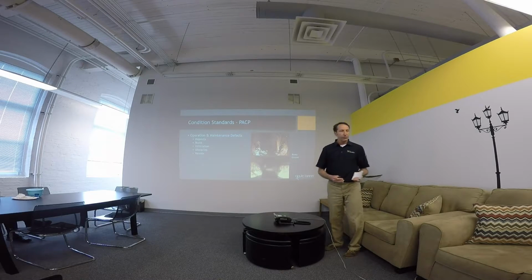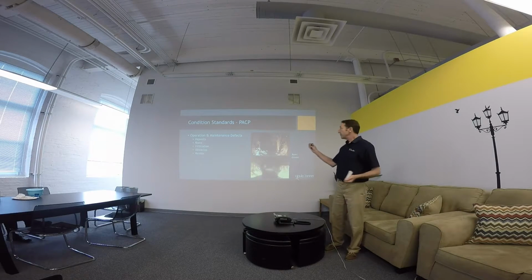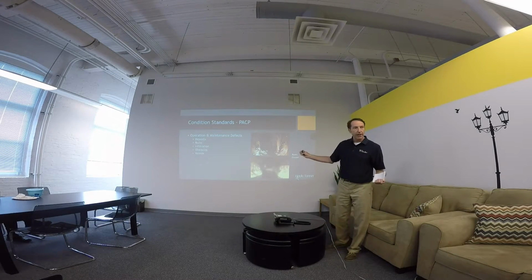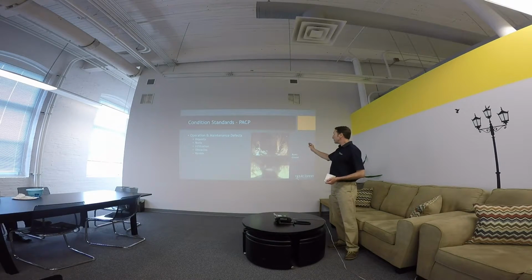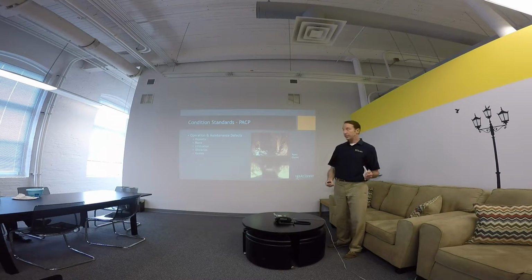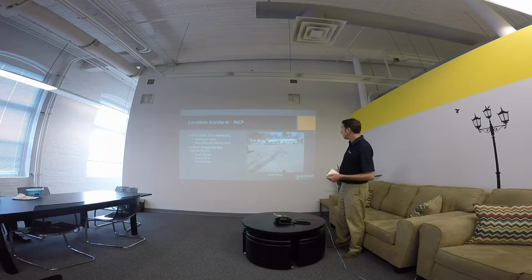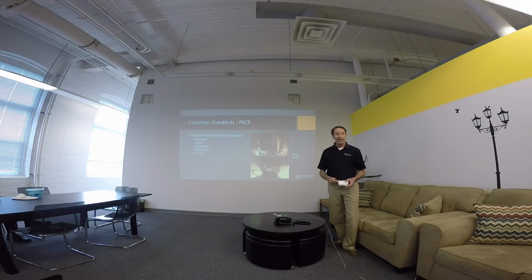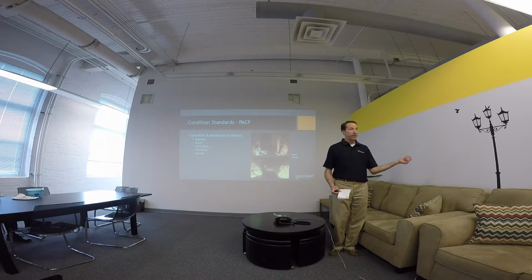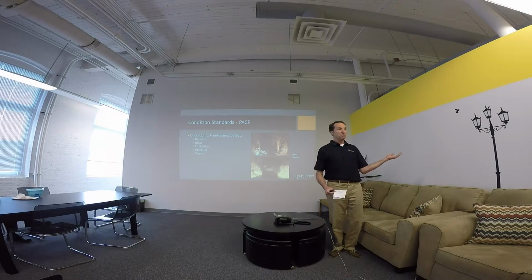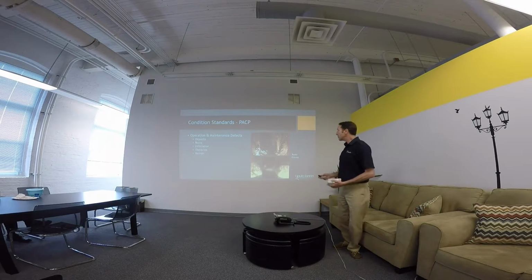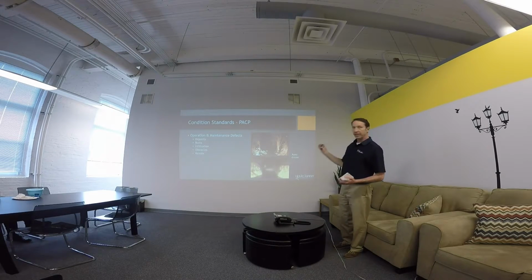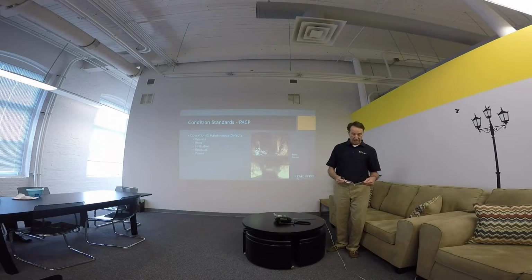I just showed you a few structural issues. I'd like to talk about the operation and maintenance defects. We have an example here that has the roots. Roots will, and you can see it looks like there's some water seeping in here. And then on down below here, you have the grease. That's actually an indication that maybe a restaurant upstream has a failing grease trap. And those are operation and maintenance defects because they can be cleaned. They can be repaired without digging things up.